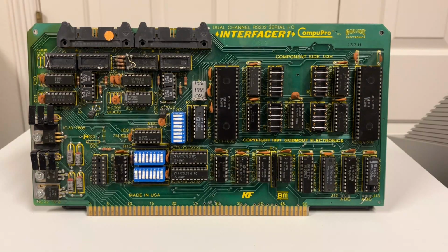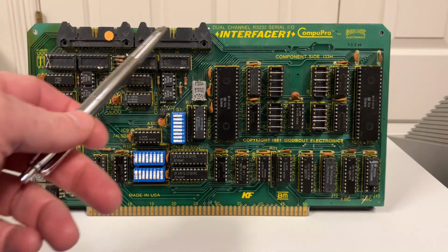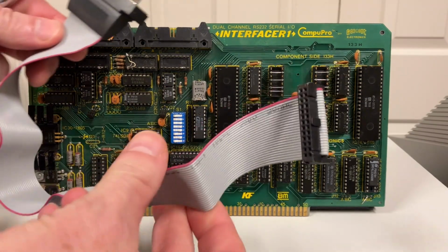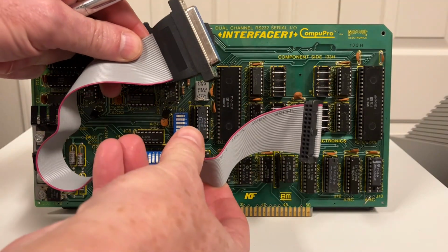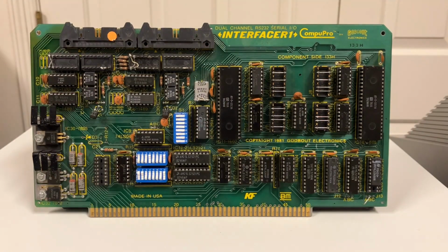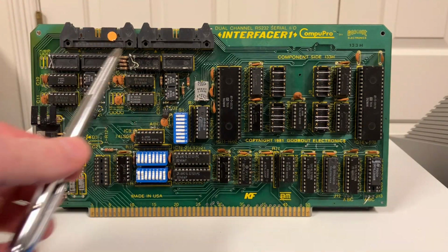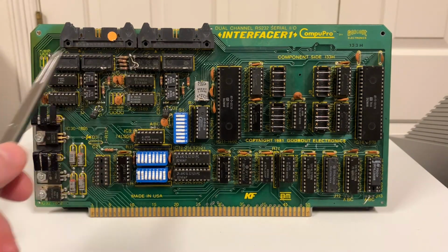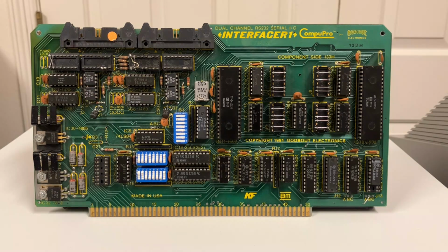All right, data comes in and out of these 2 connectors up here. These are 26-pin IDC connectors like we saw previously. This allows us just to use a standard ribbon cable like you see here. It makes it very easy to wire to the rear panel. The data for the cassette comes out of this one right here, and this jumper allows us to wire it as DCE or DTE. And so the way I have these both wired to make them look like DCE, which of course is how the cassette is defined, is the way I have it configured.